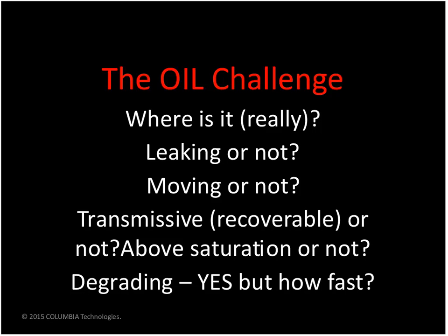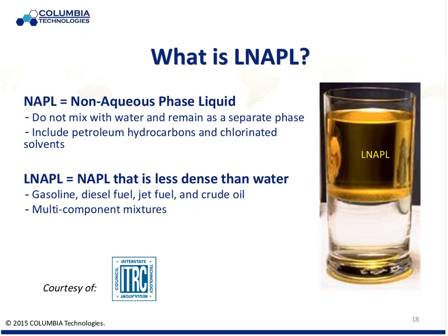And then the question, as we talked about earlier, is there a vapor issue? It's quite possible that the oil has reached equilibrium with the formation, it's confined within a footprint, and it is in fact degrading faster than we can recover it, i.e., it's no longer of sufficient saturation levels that it's transmissive or recoverable, and we really ought to let the microbial activities do their job. Could we go in and dig? We could dig and remove. That's really moving the problem to another location, but it may be the appropriate thing to do depending on the business and technical goals for the site. So those are oversimplifying the LNAPL questions about the oil.